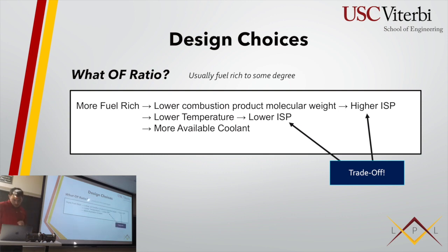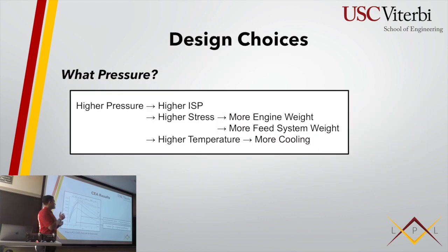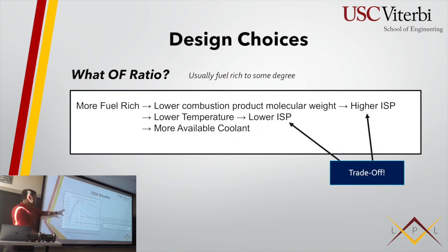Your OF ratio, usually you'll be on this line here, right? And you'll hear terms a lot of the time like, oh, you're going to be more fuel-rich or ox-rich. At least for this, you're always going to be fuel-rich, but it depends. The more oxygen you have, the hotter it gets. That's typically the rule of thumb. If you have more oxygen compared to fuel, it's going to be hotter, because oxygen, when it combusts, is hotter than more fuel. That's why for film cooling, we blast it with fuel, right? Because then when that combusts, it's not as hot. So that's the concept of film cooling.